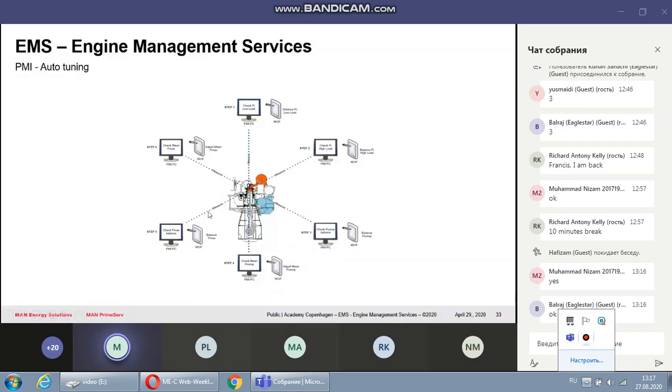The difference is divided and scaled as a percent of absolute, and then you make the compression ratio adjustment. Now the last one is your Pmax. Check the individual Pmax. Check the mean Pmax. Between these two, you find out what the difference is. Adjust it on your Pmax offset. So that is how the adjustment has to be done.